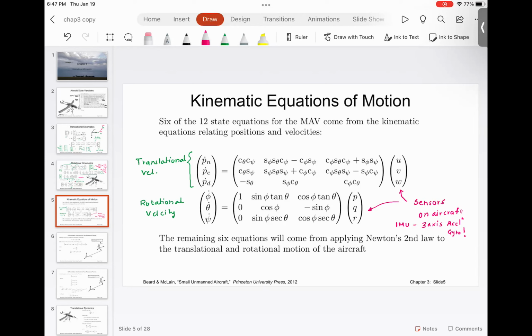At time t equal to 0, roll is 0, pitch is 0, yaw is 0. Those values are substituted in this matrix, so this matrix is known. At 0.001 second, which is 1/1000 of a second, you get an update from the gyroscope.